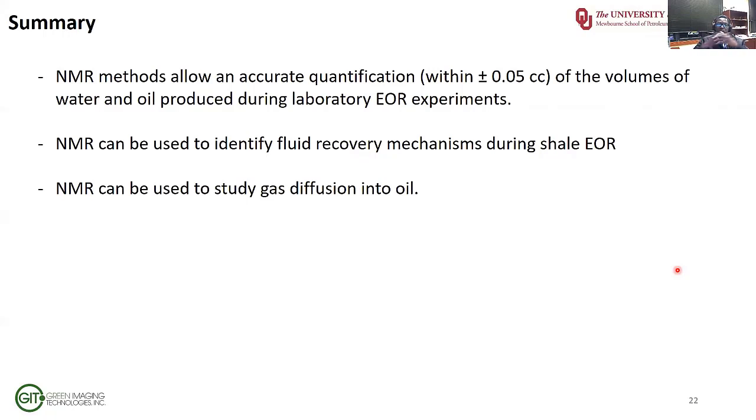And we have seen also that NMR can be used to study gas diffusion into oil, right? That's in the bulk phase. We can also do that kind of measurement, especially if we do have a gradient coil. And if we do have access to the bulk diffusion coefficient, which we can obtain from this last point over here, all we then need is a tortuosity measurement, which can also be done with NMR methods, to obtain the effective diffusion coefficient. So it seems like with NMR, we can really get a full evaluation of the EOR process.